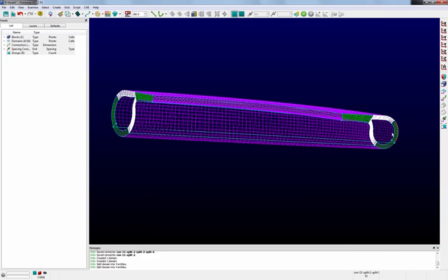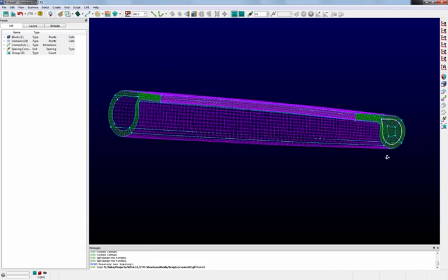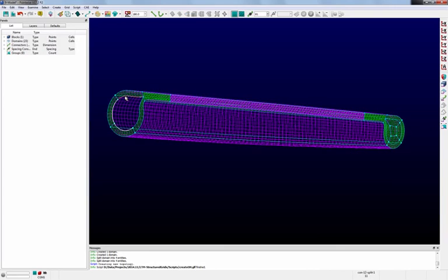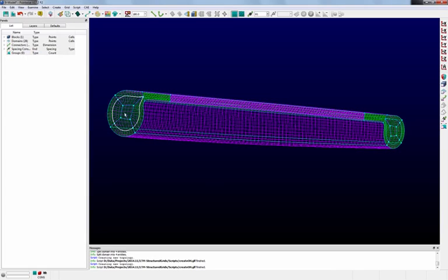The next thing that we need to do is create that OH topology, so I'm just going to highlight these 4 connectors. I'm going to go Script, Create OH, and then click Create OH. I'm going to repeat down here. We're just going to use that default value. Control-E will re-execute the script and create OH. So you now see that we have our outer topology.